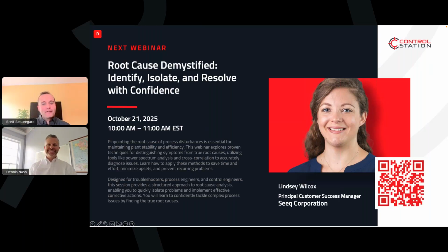Sure. Loop monitoring, yeah, we have PlantESP. We've had it for many years. We were talking about statistics earlier on to monitor and determine whether the control loop is degrading. That's the topic of a separate webinar. But yes, we have a supervisory control loop performance monitoring package that will run 24 hours a day, analyzing loops to determine if performance is degrading, if valves are sticking, if tunings are deviating from where we think they should be, and it gives you the peace of mind that once you fix something, it will stay fixed, or we will notify you if it starts to degrade from its improved state.